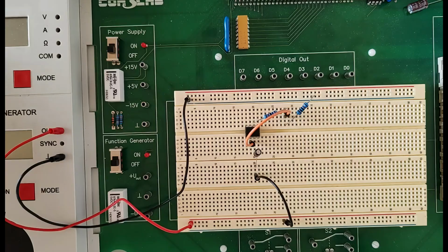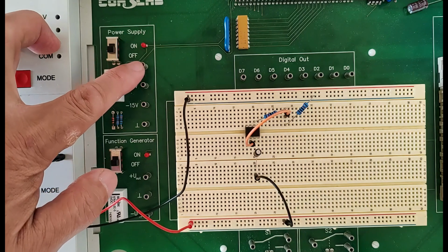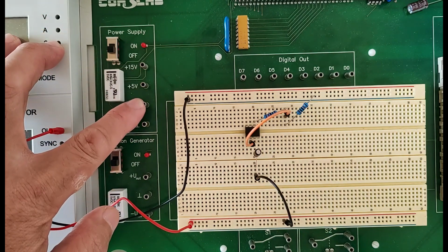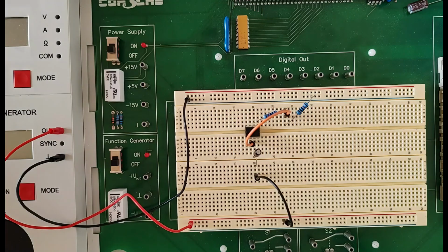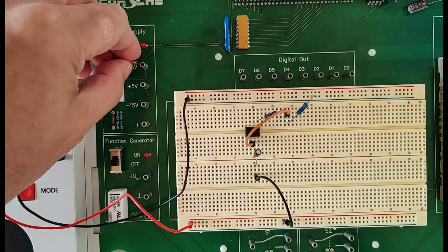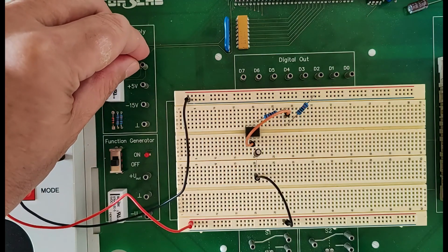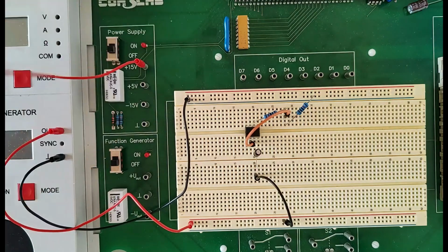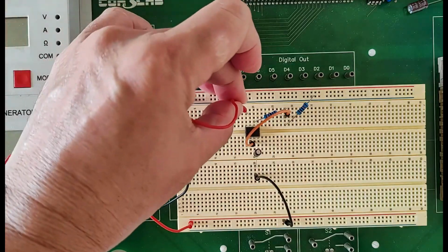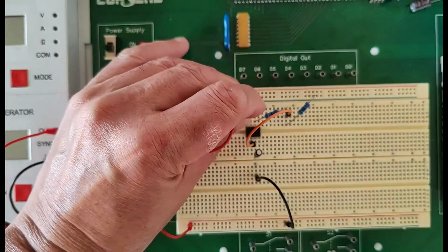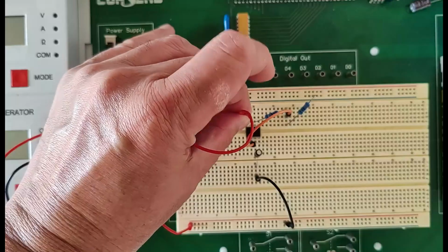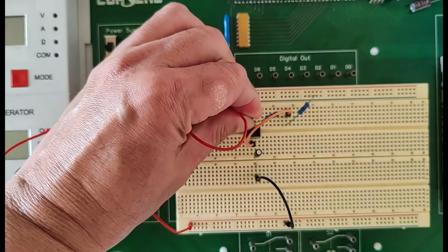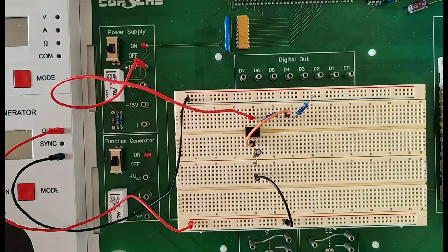Now, what's left here are the connections of the power supply pins of our 741, okay? Which, according to the schematic diagram, will come from here. Positive 15 and negative 15 from here. So what I'll do right now, I'll connect positive 15. You can remember the diagram before. Positive 15 will connect to pin number 7. Do that now. Pin number 7. Here. Pin 7. There. Okay.